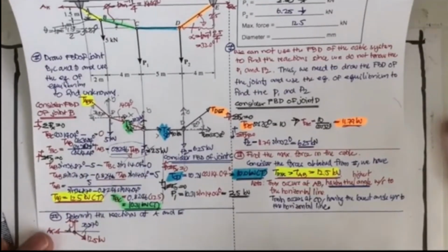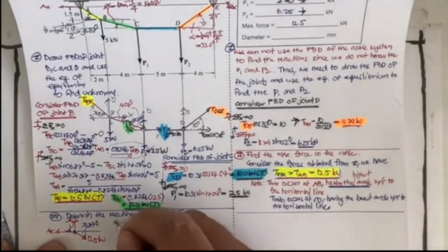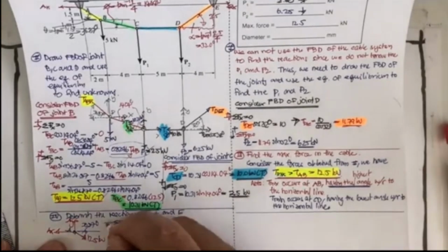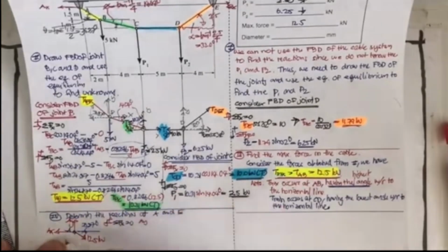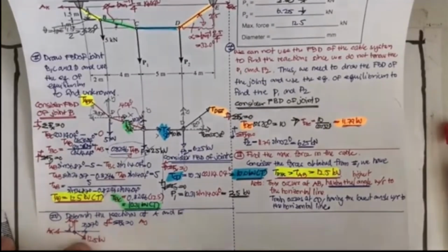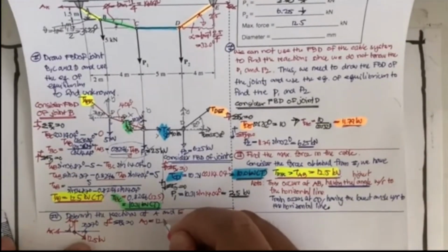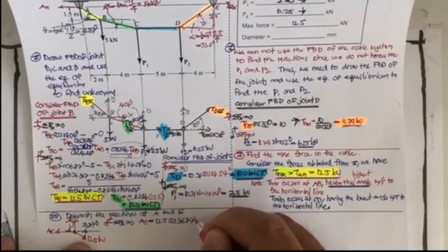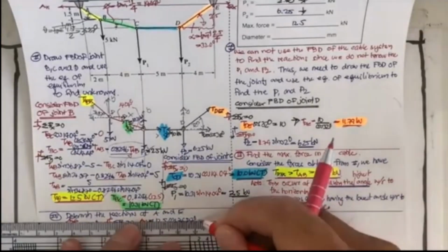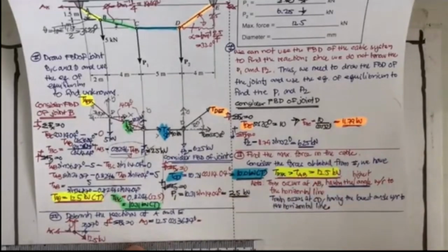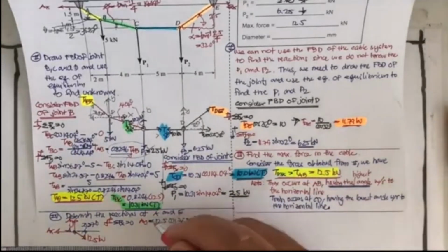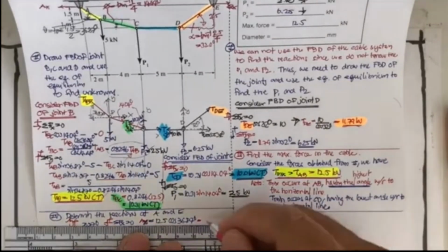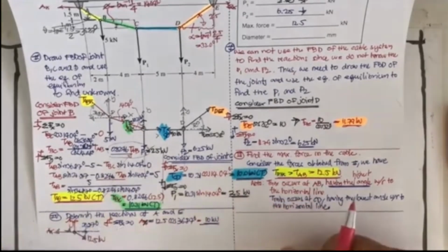By considering this, you may determine the summation of F sub x equal to 0. That means you're going to project this, and then you put this one plus, so your A sub x right here, and this one is going to be cosine, so it's going to equal 12.5 cosine of 36.87 degrees. So you can get A sub x easily, A sub x equal to 10 kilonewton.